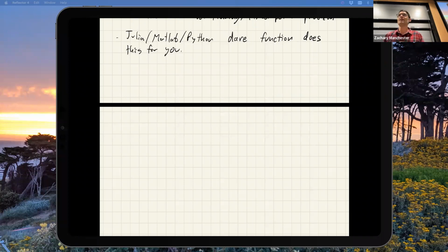There are some pretty impressive demos from a few years ago from Atlas, Boston Dynamics, where they do LQR with it standing on one foot, and then hit it with the classic shove of the robot. It does incredibly well. It wiggles around and balances on one foot, just LQR in joint space.